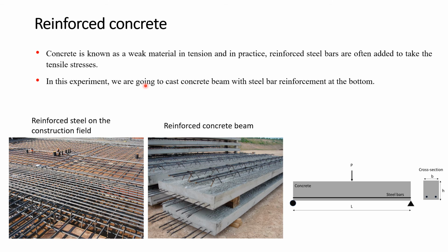Reinforced concrete. Although concrete is pretty strong in compression, it is also known as a weak material in tension, and that's why in practice, reinforcing steel bar is often added to take the tensile stress. That's why in the construction field, you see many reinforced concrete structures, and in many cases you can see concrete working with steel. In this experiment, we are going to cast a concrete beam with steel bar reinforcement at the bottom. That's because the bottom is where the tensile stress is applied.